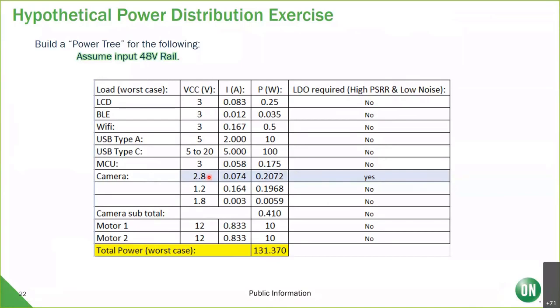So optionally, you can put a bunch of decoupling near the chip, but that's only so good because the chip is fairly big, and it's hard to decouple well when you've got such noisy potential. So you can also put MIM caps on the chip, but that does increase the cost. So typically, image sensors like to see an LDO, which has really good power supply rejection, and it really gives you a really good DC level of 2.8 volts.